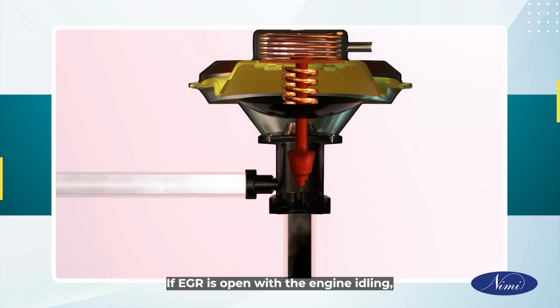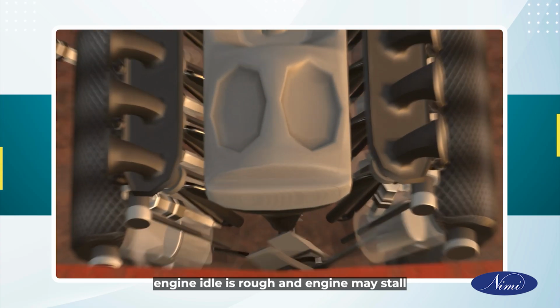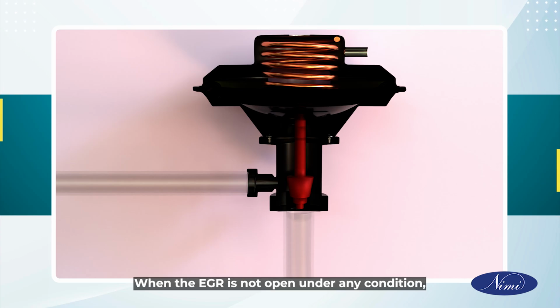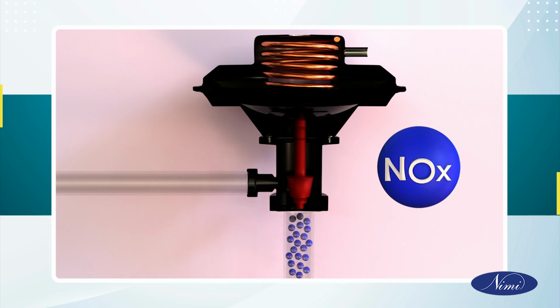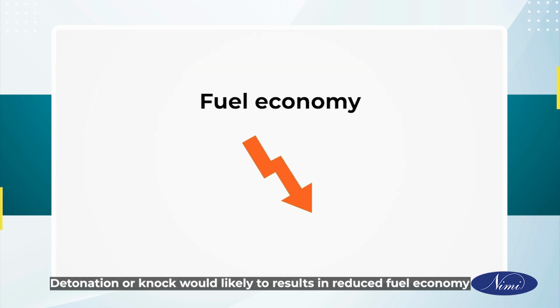If EGR is open with the engine idling, the engine idle is rough and the engine may stall. When the EGR is not open under any condition, NOx emissions are high and engine detonation may occur. Detonation or knock would likely result in reduced fuel economy.